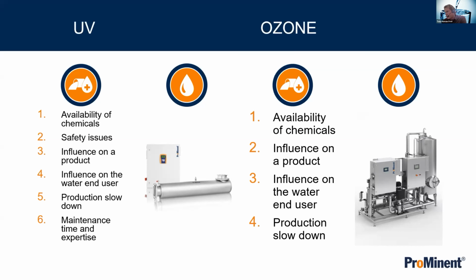Why? Bottled water, if we treat that with anything else but ozone or UV, we would get influence on taste and smell. And nobody wants to buy a bottle of water and then have that nice pool chlorine smell if you open the bottle. You're not going to sell a single bottle of water anymore. So again, ozone also, if you put it at the beginning of your pipe work or a long residence time of your water in a tank, you're not going to have that residual protection.